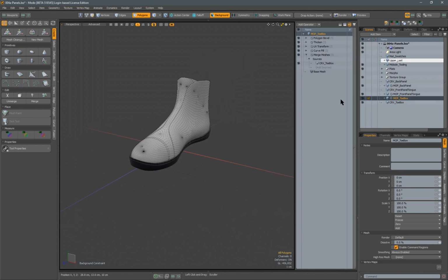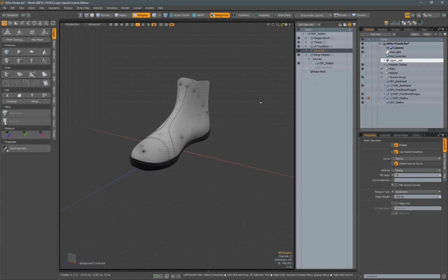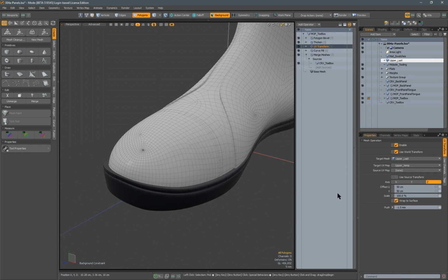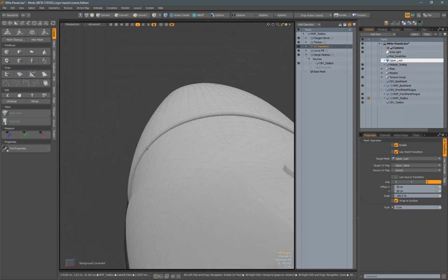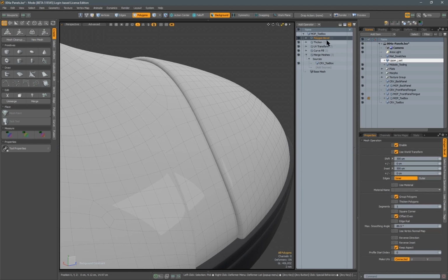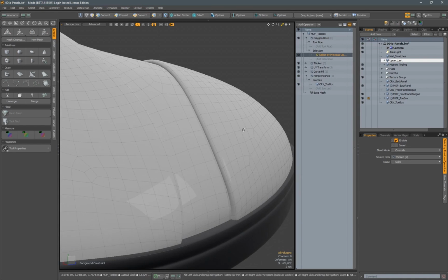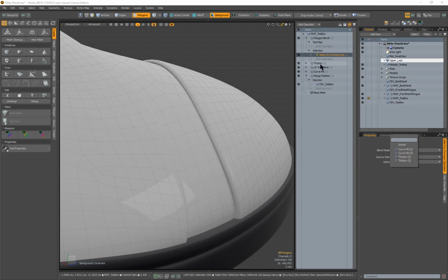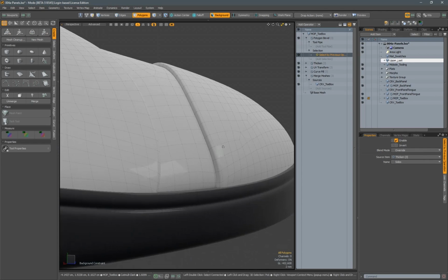All right. Now let's go ahead and go back to the toe box item. Go to the curve fill mesh op, and make sure everything is good in here, and it looks just fine because it came from a duplicated mesh item, so we should be good to go. One thing I do want to change here is that on the UV transform, let's turn off the push. Let's just set that to 0. We also need to go into the polygon bevel, expand that out, and then select by previous, and then make sure that it is selecting the correct thicken here. So it should be thicken 3, not thicken 2, and now everything is good to go on that panel.